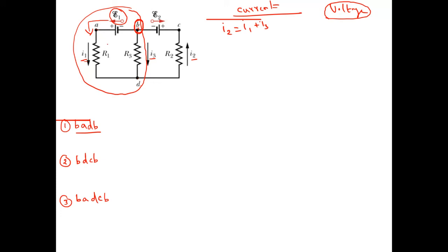Okay, could you please write? I am going to separate the battery and the current and the resistance. So I have only one battery. So how can I write? E1 is equal to, my direction of the current, this current is also in the same direction, so it is positive, I1 multiplied by R1. And then you come here, and this current is opposite to this current, so it is negative: minus I3 R3. Clear?